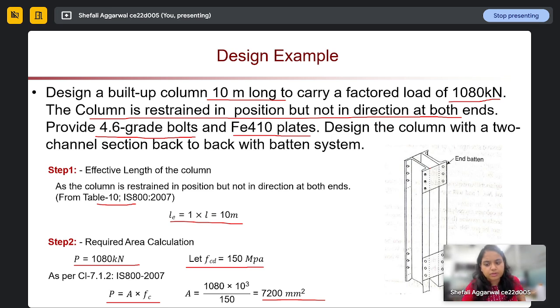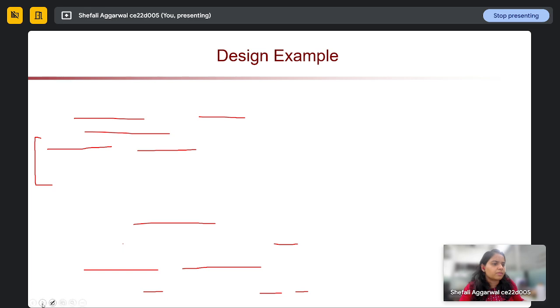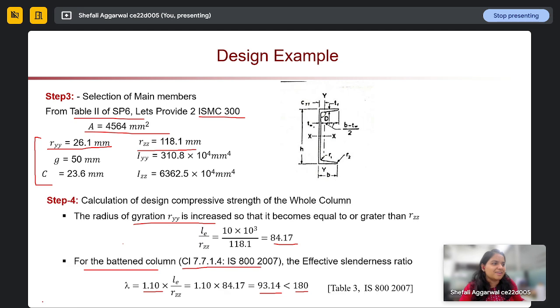See, ma'am, transverse shear is what we are getting perpendicular to the load. So according to that, in the lacing system, with cos theta, whatever the angle, we are separating it. That is fine. But in this, the batten is perpendicular to it. Transverse shear is what we are generating along that direction. Why has this longitudinal shear newly come into the picture? Did you get my question, ma'am?